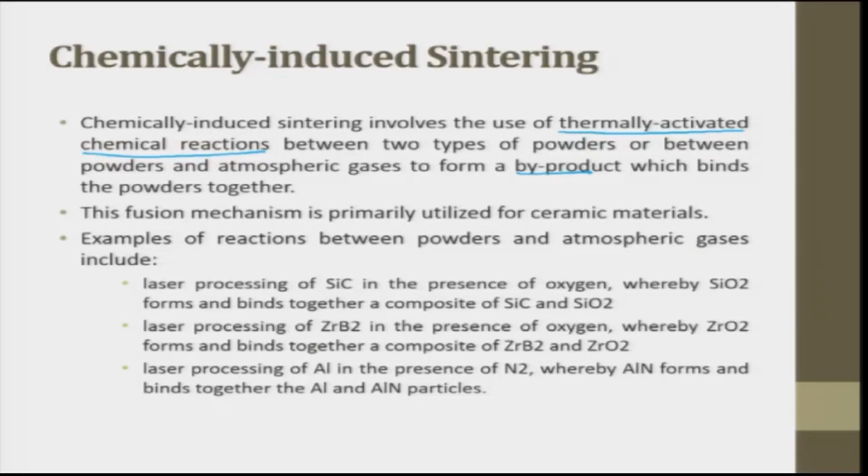So here there is no chemical reaction, but we add a binder in between which completely covers the small particles, and then it tries to go in between. If you have it in a solid state, it is very difficult to mix. So what we do is we heat the ghee, bring it to the liquid form, and pour the ghee so that all the laddu particles are properly coated. Then we catch it by hand or we put it in a die to give a shape. So this thing is called a green strength product.